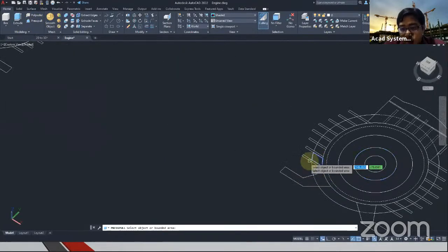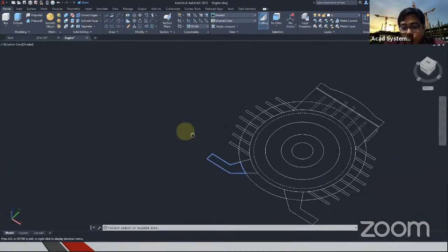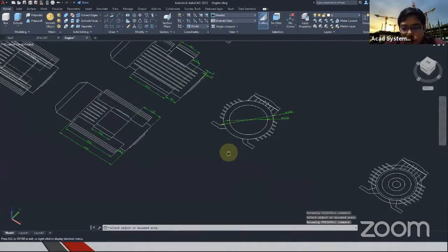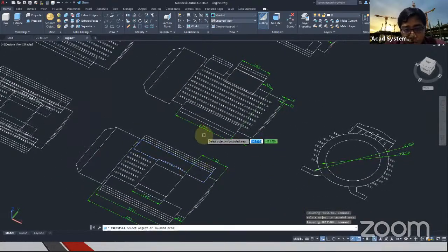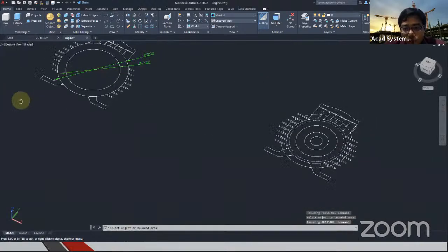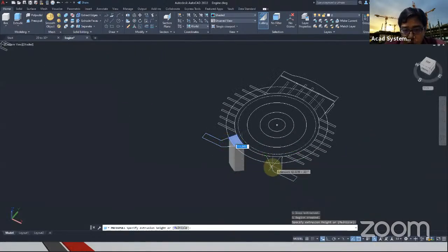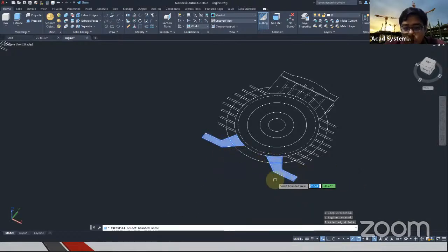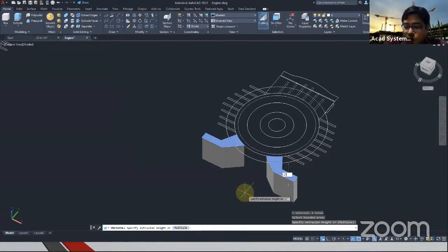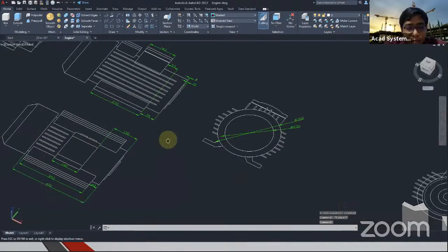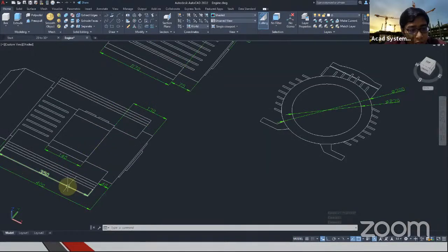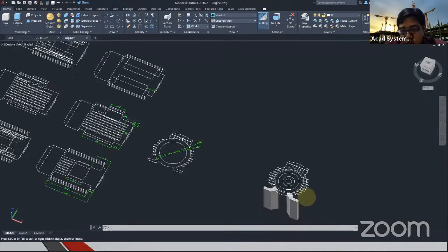And we can start to press pull our entire shape over here. So let's start with the leg. For the leg, you can see from the sketch, the length of the leg will be 270. So I will start to select the leg, select multiple, so I can select multiple legs that I need. Enter and enter the value 270. Then I can move on to the next one. So this particular rate over here, the line will be 350. So we can do that.